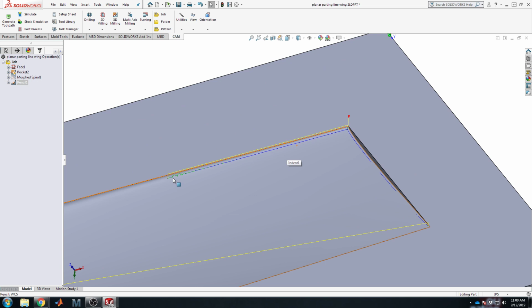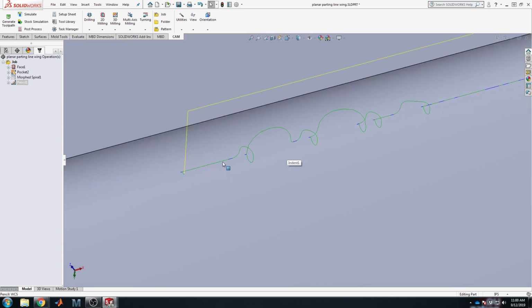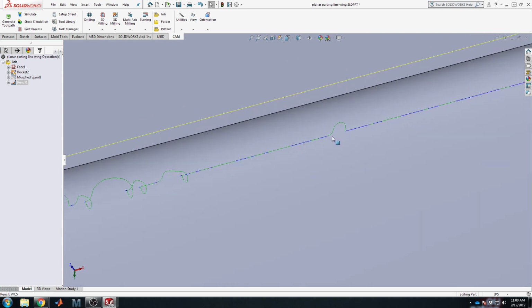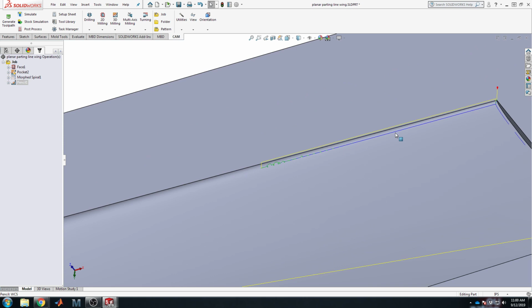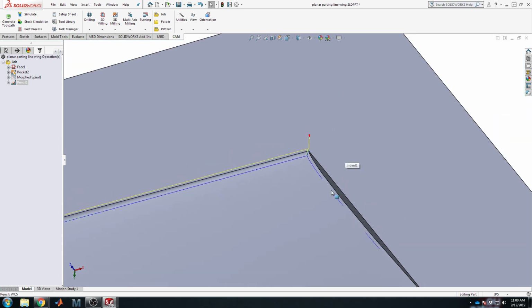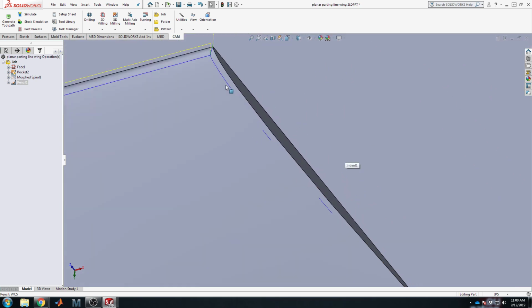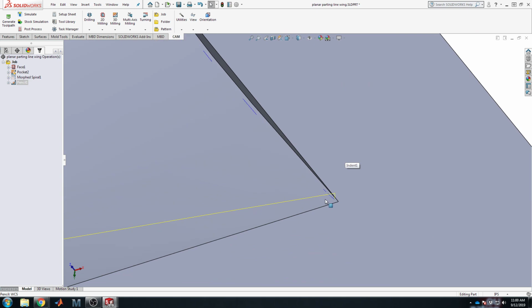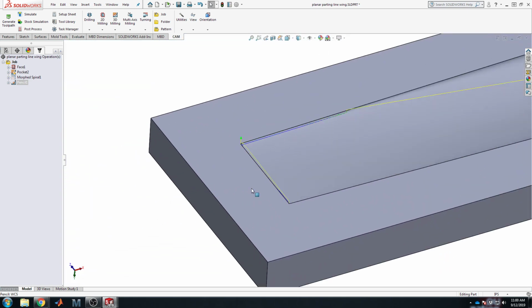Down here in the sharper corners, you see it's doing some, I would call that odd machine code remnants. That's garbage. But unfortunately, it won't do any harm. It'll just take the machine a bit longer. But over here, it's going to travel down that sharp curvature region. It's going to go up into the corner to take care of that. It's going to go right along this harsh edge left by that large 2-inch mill bit and do the same on the other side.